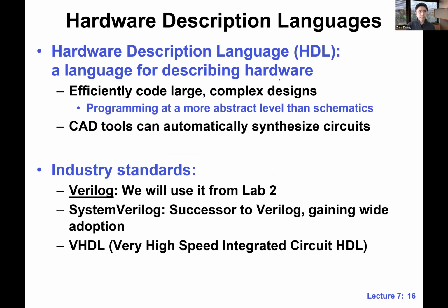All right. So coming back to Verilog or HDL. Like I mentioned, this really enables us to build much more complex designs. If you keep doing the transistor level, if you keep doing the manual wiring of those gates, that's just too time consuming and too error prone. And like I mentioned in one of the classes, you're not going to be building a more efficient circuit than the computer. The computer will be running all sorts of algorithms to optimize and minimize the multi-level logic, not the two-level, not using Karnaugh maps.